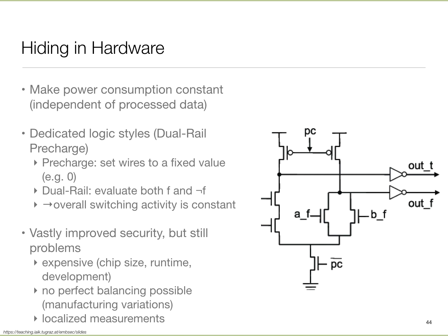The idea is that as a result, these circuits have two different pathways. If you see, I have a series out here and a complement parallel out here. So I really have two back-to-back gates, and at all times something here and something on the left side will get activated, so that the overall power profile remains constant. So these are called dual rail logic.